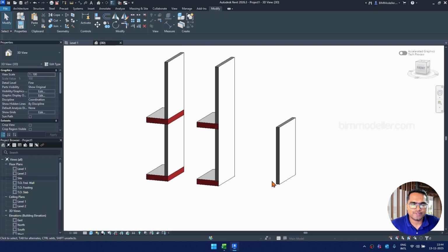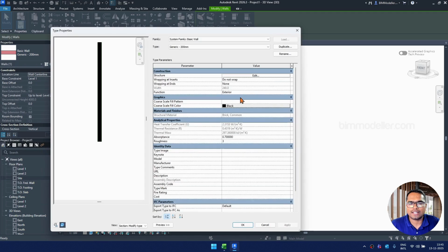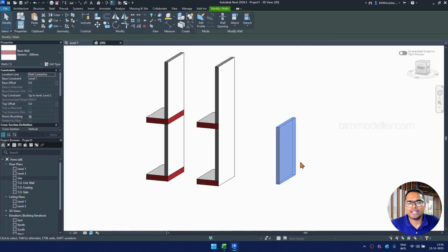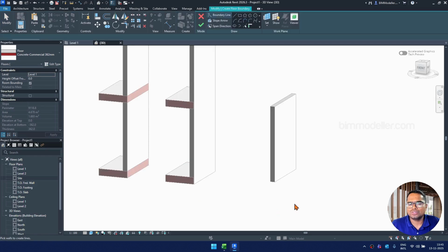That's the video. So let's say we have a wall. In the wall properties, you must have an internal structure, which would be bricks or concrete or whatever thickness that you have. Then make sure that the finish goes beyond that core boundary. Once the wall settings are done, you know that plaster is not a core boundary. And once it is done, create a floor.